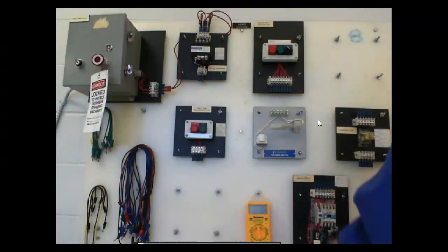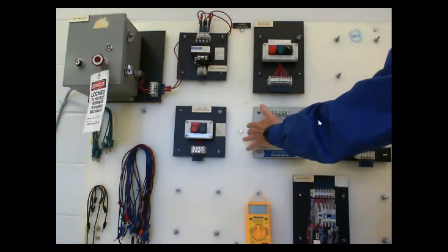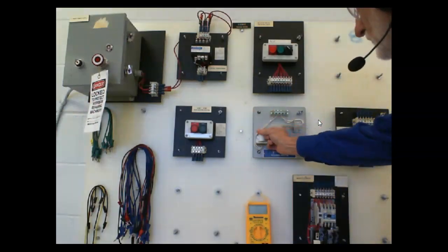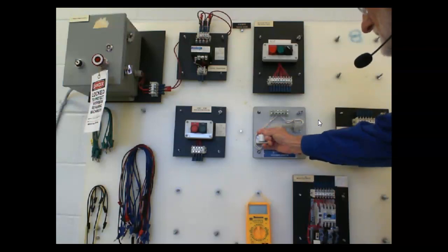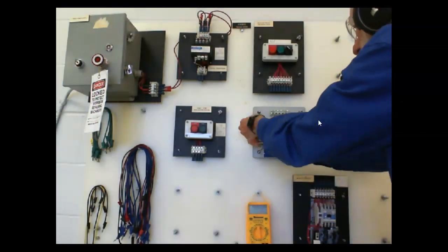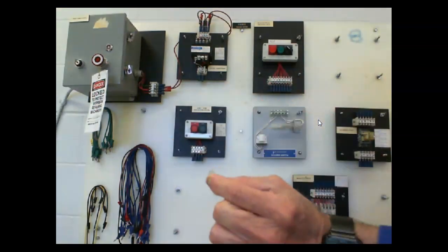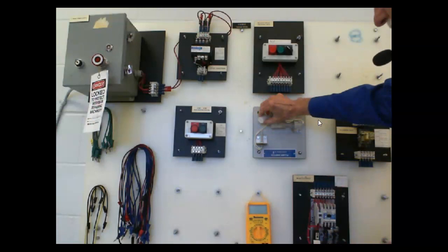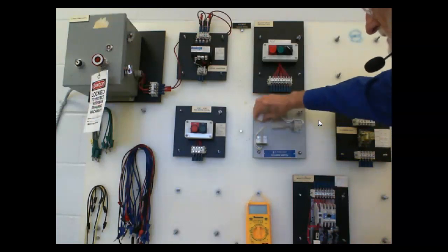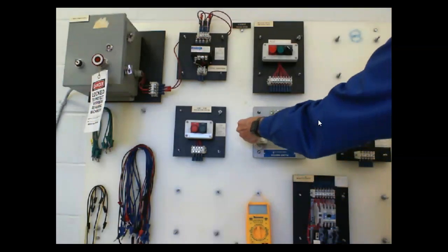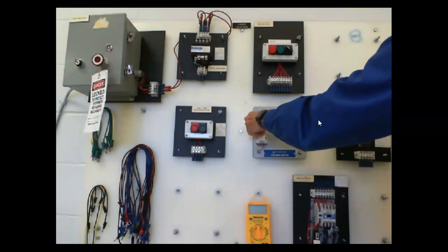And this is our liquid level switch. We've actually got two. This one we can change from a normally open to a normally closed, or vice versa, by snapping off this little plastic ring, or washer, which would be this guy. Then we would just take it off and turn it around. So right now I have it set up to be normally open with the panel mounted upside down.